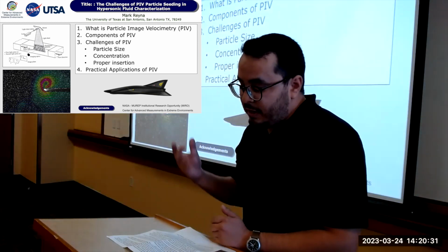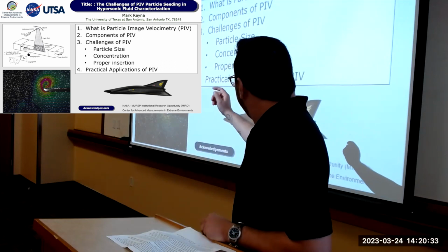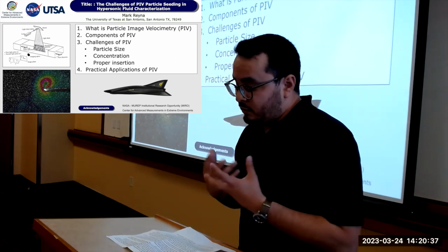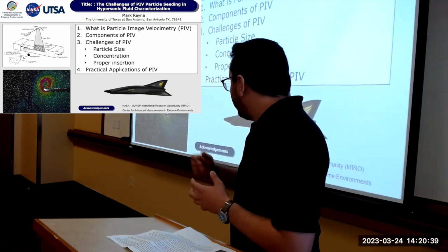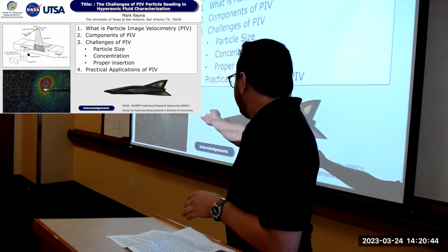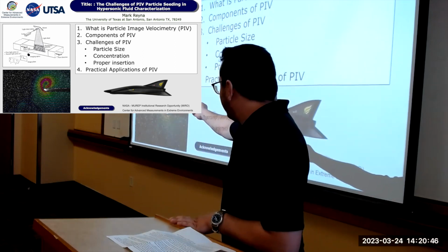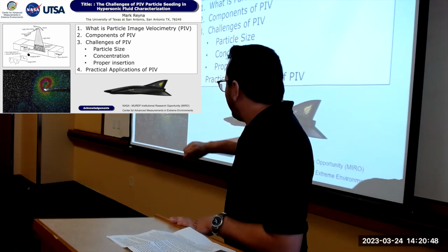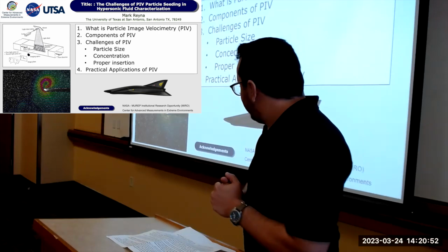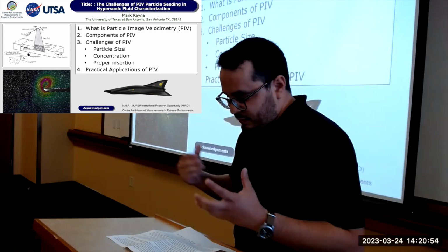In this photo here, you can actually see what 2D PIV looks like. This is a representation of vortices forming around an oscillating plate. So in this image, you can actually see the red colors are high speeds versus the green, yellow, and blue are lower speeds, whereas the black is typically not moving.